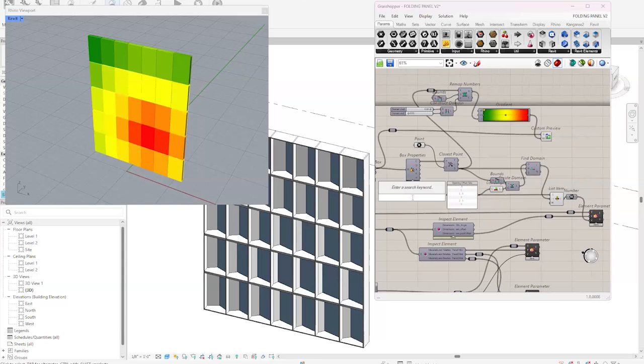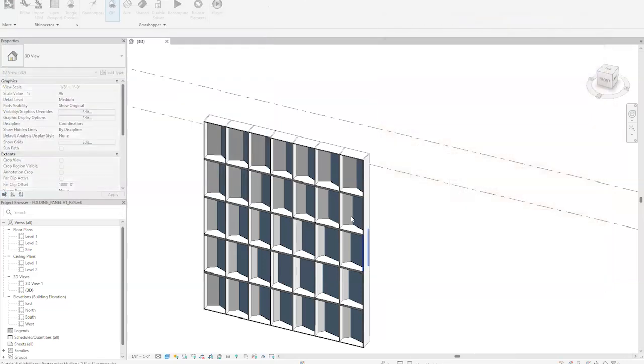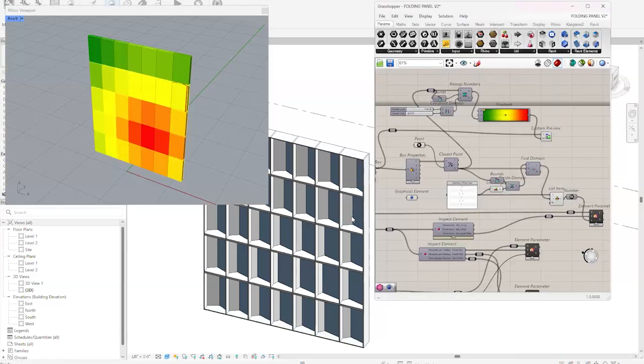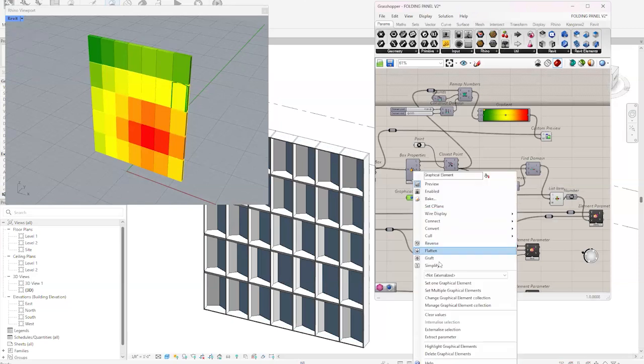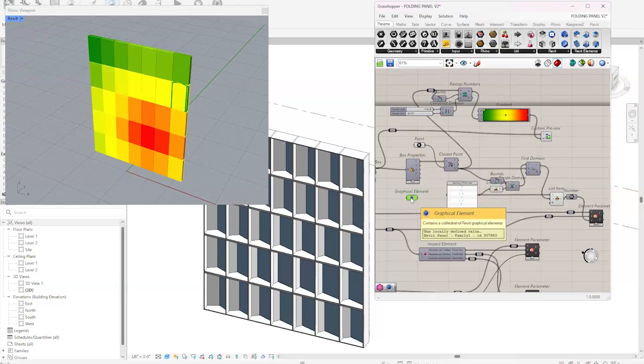At any time, you could place one of those on a canvas, set something, and then bake that right into Rhino. That's really handy for people that are doing highly detailed parts where the Revit's not as detailed. So you bring a section of the building into Rhino and then create more detailed items and then push those back into Revit for documentation.